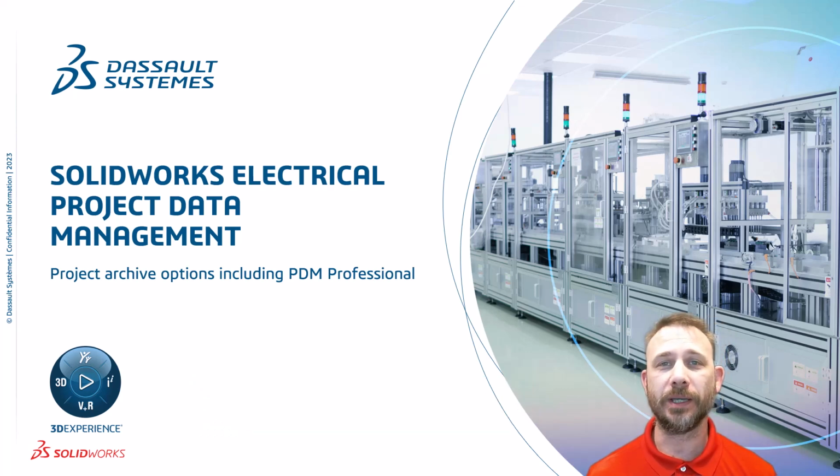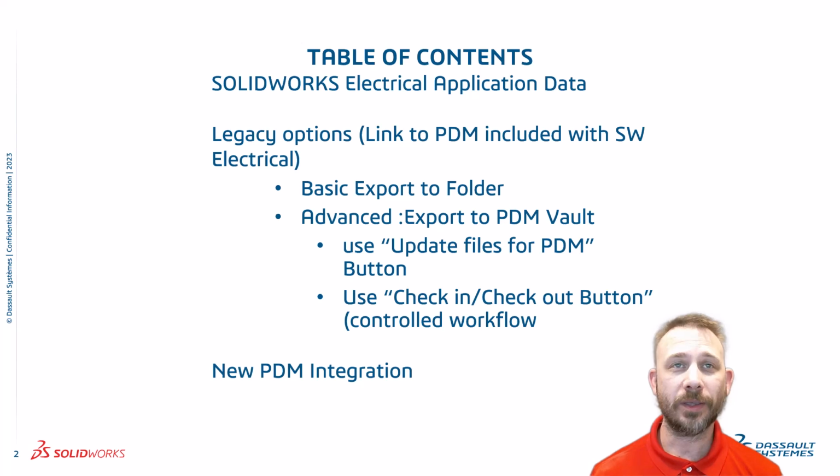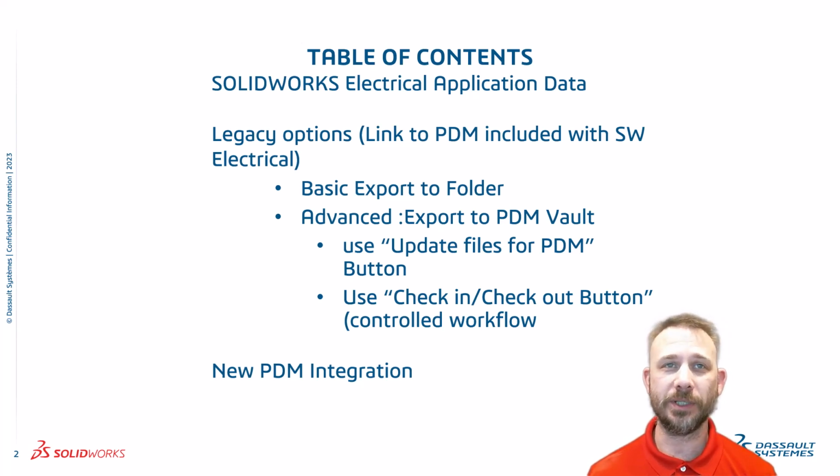Today I want to discuss with you guys the ability and the options that we have available for storing SOLIDWORKS electrical projects within PDM Professional or even in a single file folder structure. Today I wanted to discuss the ins and outs of the SOLIDWORKS electrical application data, where it's stored, what it entails, and then we're going to discuss the options that are built into SOLIDWORKS electrical, which I call the legacy options, which include a link to PDM, base export to folder, and the advanced export to PDM. Use the update PDM button or the controlled workflow with the check-in, check-out buttons.